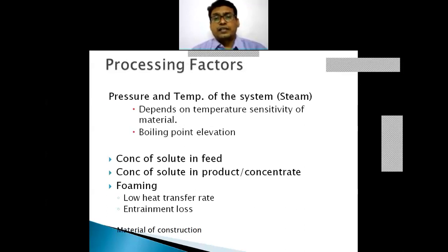These processing factors are the pressure and temperature of the system, which depend on the temperature sensitivity of the material and the boiling point elevation. Then the concentration of the solute in the feed, the concentration of solute in the product, then the foaming characteristics and the material of construction.